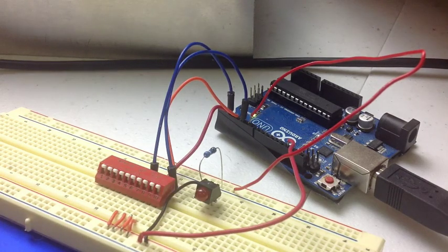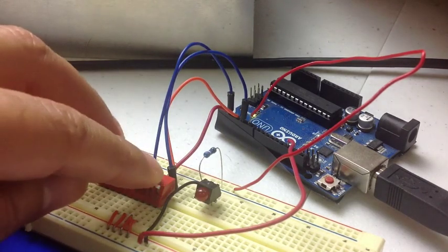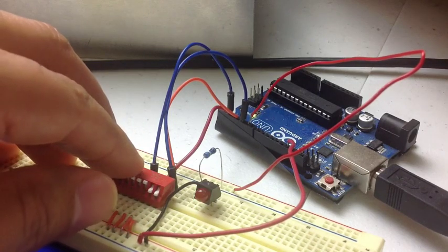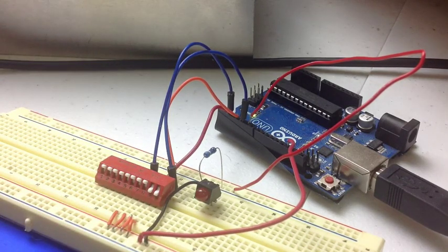Okay, so I have successfully downloaded my program onto the Arduino, so it's actually currently running right now. It's not obvious, but remember I mentioned that the state that you're most likely to be in is the state when you're all zeros. That is, there's no change. So as long as you've been watching, there's been no change, and so the light has been dark. So now I'm going to flip a couple of these switches. The light goes on for 1 second. The next second, when it checks, there has been no change, and so it goes off again.